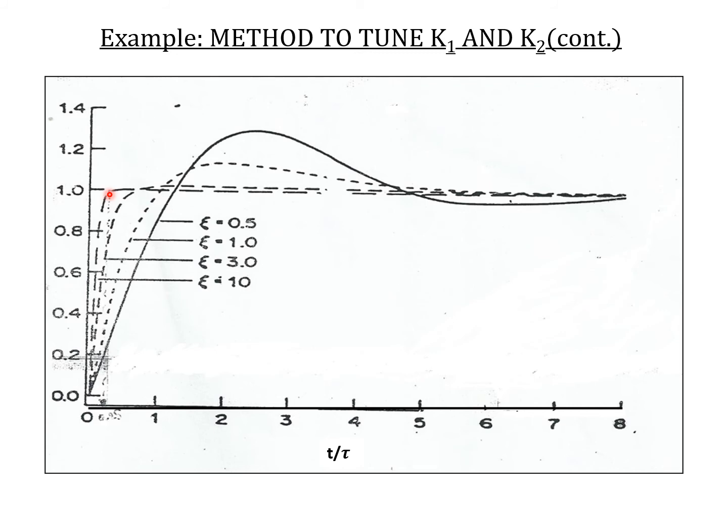And this is a normal, typical graph that we use to get roughly the K1, K2. This is again just like we do for tuning using Nichols and so on. This is roughly an initial estimate for the tuning. After that, we may need to fine-tune it a bit more to get a better result, to get more of the profile that you want, the overshoot or time of response that we want. We may have to fine-tune a little bit, just like Nichols and other methods. These are initial estimates, not the perfect estimate, of course, because there's a lot of inaccuracy in this.